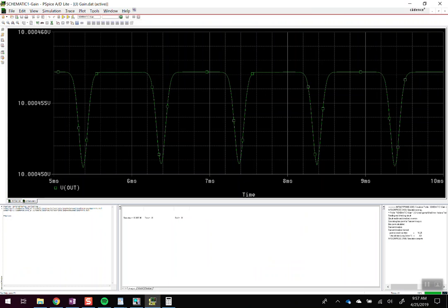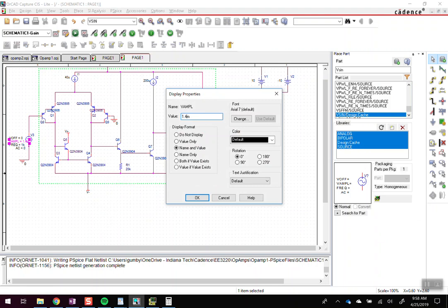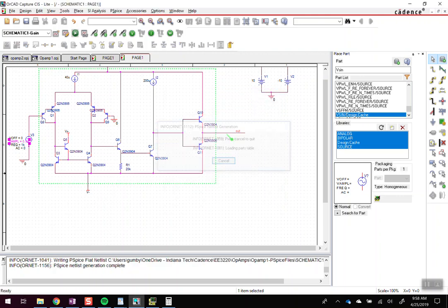And you see we're getting a weird signal here now in the output, because what I've done essentially is saturate it at the positive rail. So let's even go for something smaller here. Let's try 0.1 millivolt.